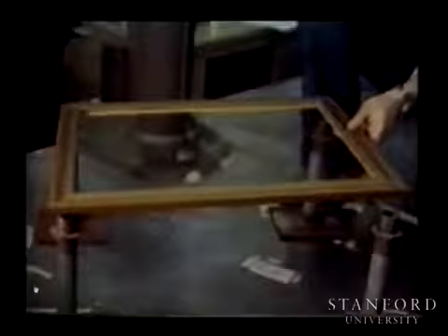All of this cannot be done without force control and compliant motion control. So you put in an error and still you are doing the same task. Dealing with uncertainties requires you to be able to control the compliance. This is linear compliance, but we can also do rotational compliance. So zero moment. When you push to the left or to the right, you will have a zero moment. So if we could see the video back.